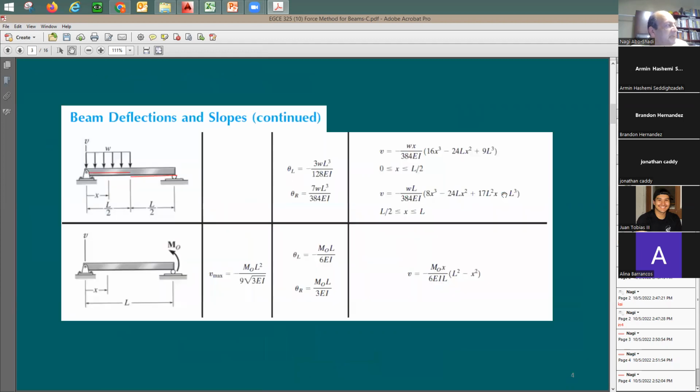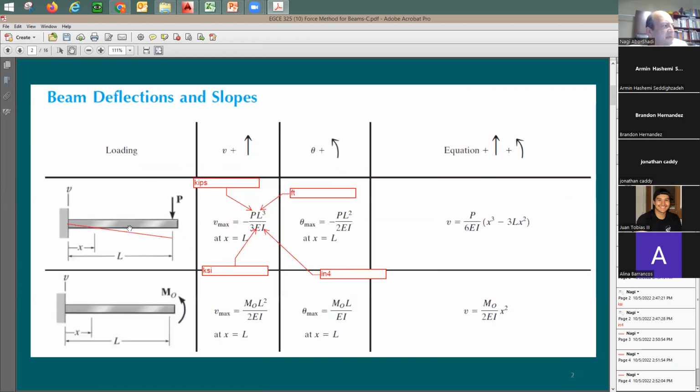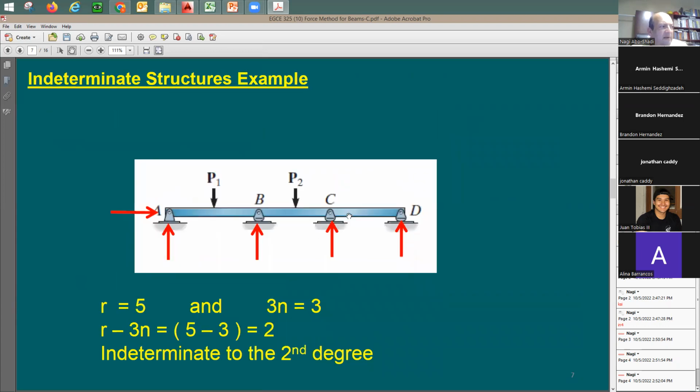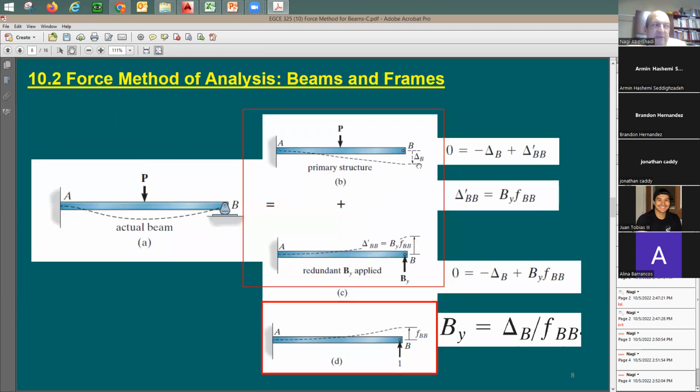I need to find a case, something like a cantilever and things like this, right? Otherwise, it's going to be tough, it's going to take time. I need to go to the conjugate beam or maybe the virtual work and spend some time, but I don't want to do this. So I'm going to go to the pre-solved examples, the standard beams, and just pick the deflection from there, do the math, do the analysis for it.